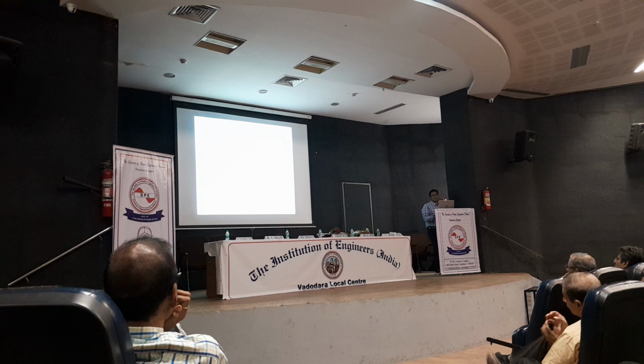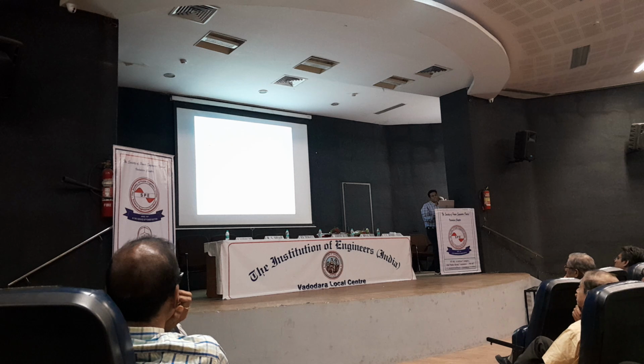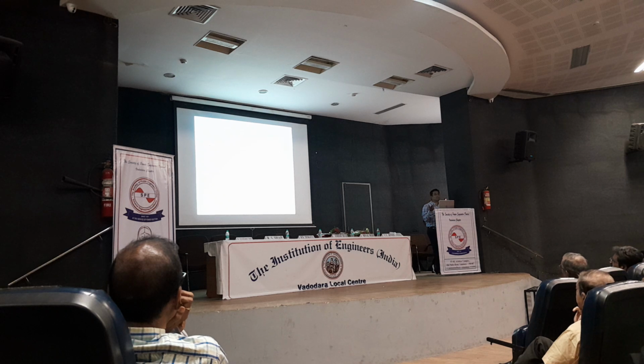If you pay attention to the bus number 5 side values, you will find the receiving end active power is 53.698 megawatt, and the reactive power value is around minus 7.16 megawatt ampere reactive. Whatever is sent and whatever is received, there is always a difference, because there is a distance, and over that distance you have the transmission line. If you enter the resistance value as 0, then it will be a lossless line, so you may have 100% efficiency.